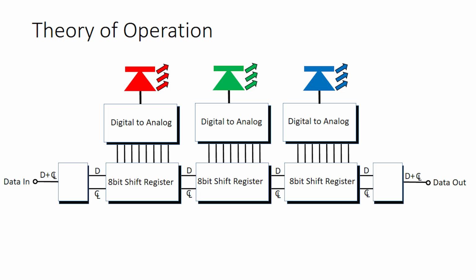Now that output one's important for a reason that I'll explain later. Apart from recombining them, it stiffens it up. It makes sure the timing's correct. It makes sure the pulse is the right height and the right shape, which means that the pulses coming out of your microcontroller aren't getting degraded as they go along the NeoPixel chain. Every NeoPixel straightens up the data as it sends it to its neighbour. So the data that comes out of the last NeoPixel is fresher than the data that you put in the front end.